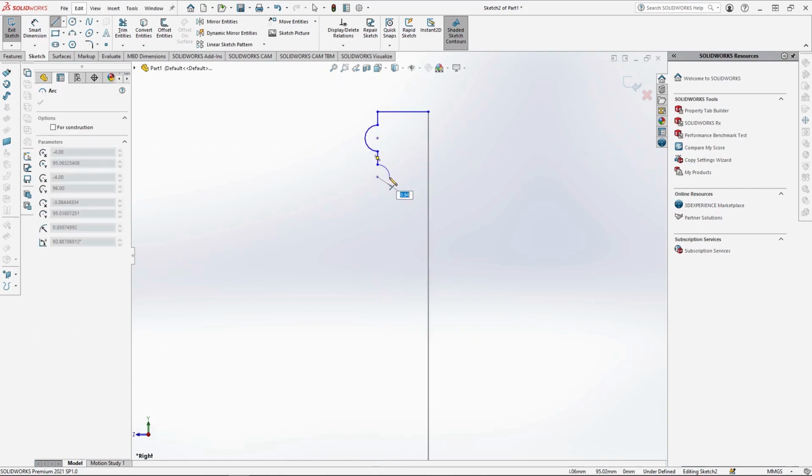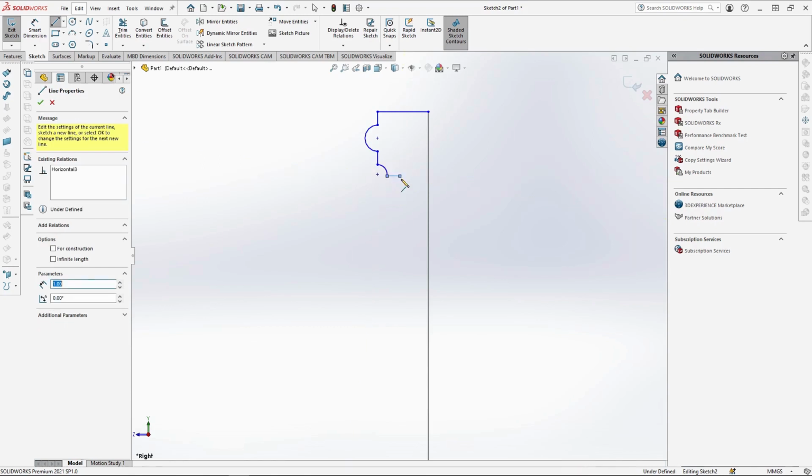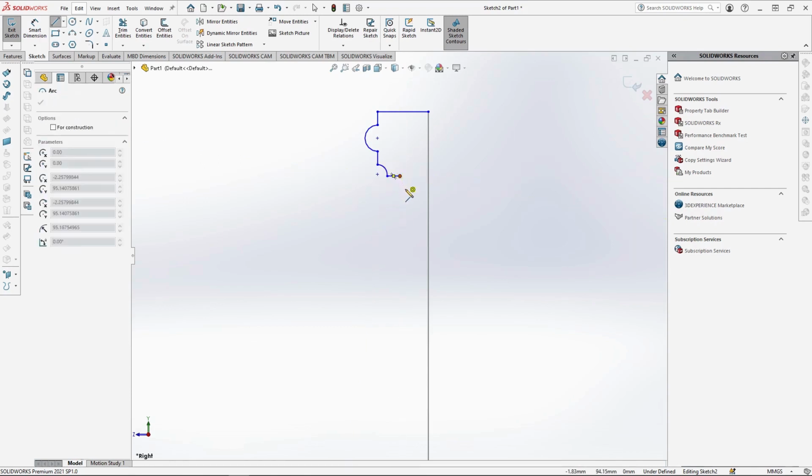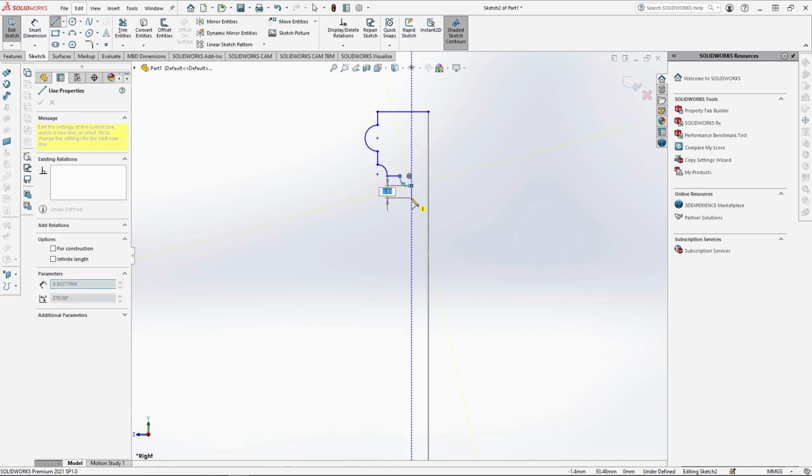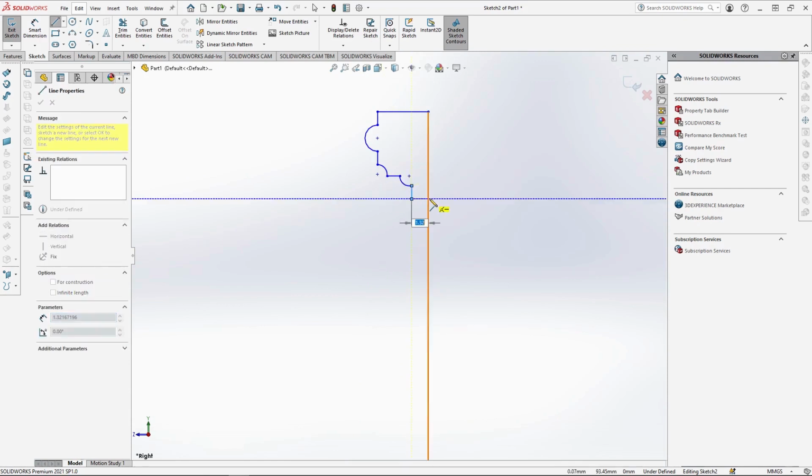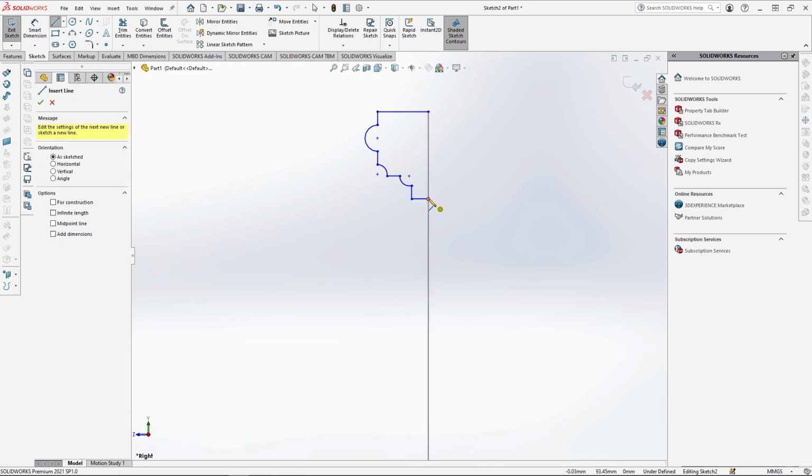semicircle with a 0.75mm radius. Then in by 1mm, do another half semicircle going outwards with a 0.75mm radius. Go down from this by 1mm, then finally close off the profile.